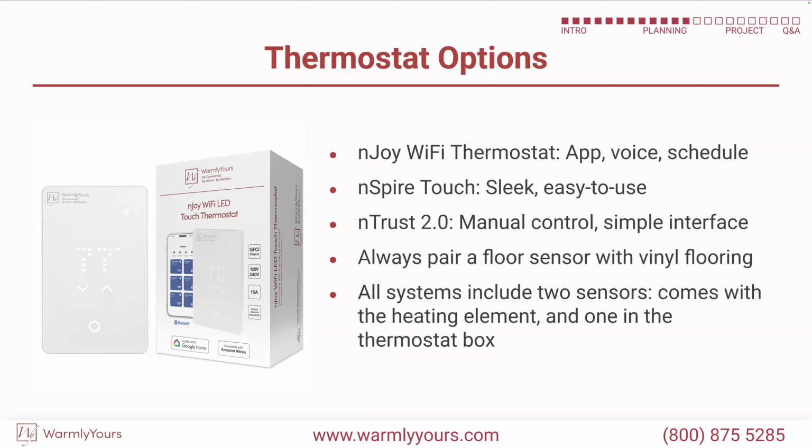But at the beginning of the heating season, and at the end of the heating season, if you're starting with a 70-degree floor and you want it to get to 85, you just don't go, okay, it's Monday, I'm going to set this to 85, and tomorrow it'll be 85, 15 degrees warmer. Can't do that. Depending on what the manufacturer of the flooring says, you can do 2 degrees today, so you're going from 70 to 72. Then tomorrow you're going from 72 to 74. Then the day after that, 74 to 76, and on the way up to 85 or 84, wherever you want it. And it's the same way at the end of the year. At the end of the year, you're going from 85 to 83 to 81.